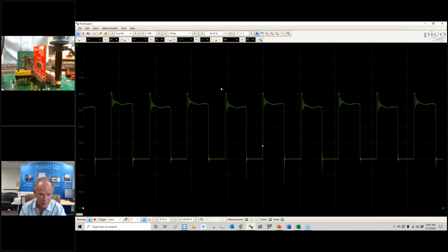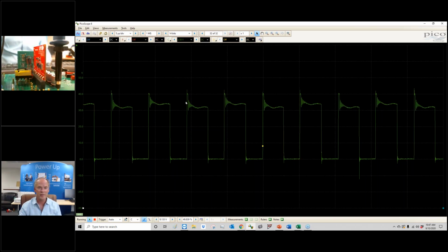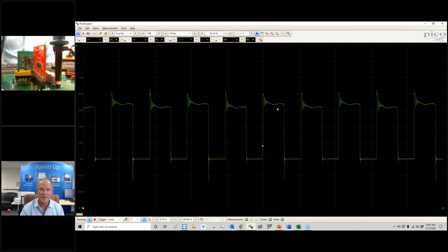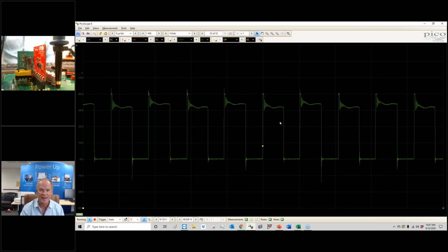And you see we've got some work to do on snubbers there. There's an interesting bouncing around with this topology. You see that low frequency bounce there in between? This is the midpoint of 2 transistors which are off. So just a little bit of twitching on this ring cycle, and they end up in different places from one cycle to another. This is not necessarily an instability.